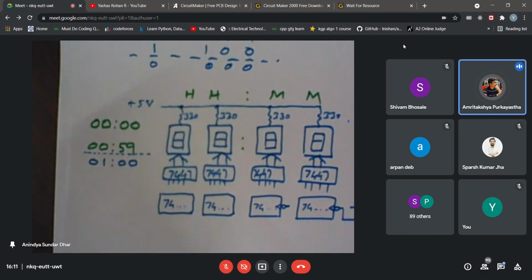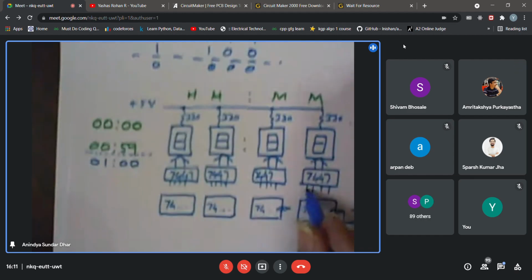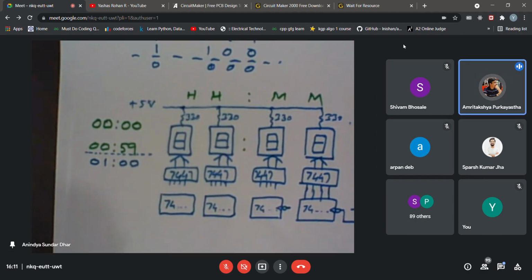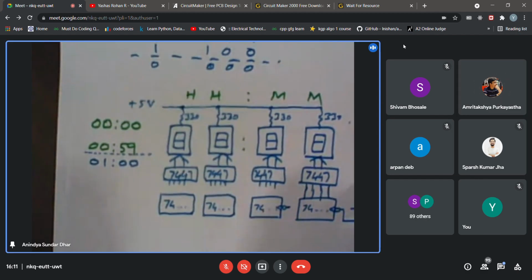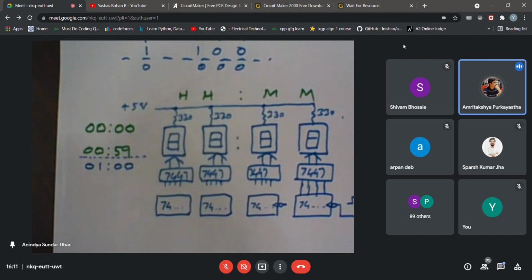The output of the first counter. Outputs are actually going over there. There are 4-bit outputs going over there. So when that would be reset, basically, the output is going to be reset after 9, whenever it reaches 10. You can just use the MSB of the first counter.